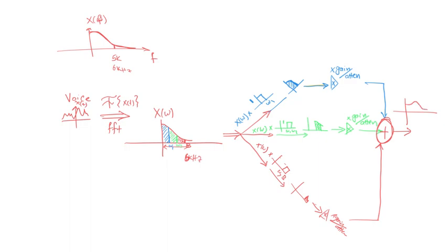Okay, whatever. You increase the gain in some parts. Let's say you pick the middle one, you increase its gain. You pick the first one, you decreased its gain. And the last one, maybe you didn't do anything to it, so it stays as it is. When you combine them, in terms of magnitude, it's going to be a differently shaped spectrum. All of this is on the magnitude of the spectrum. Okay? So we started here. This figure is the magnitude, not the phase. You don't touch the phase. Okay? And then at the end, you take the magnitudes, you combine them, and you multiply them with the phase as it is. You don't touch the phase.